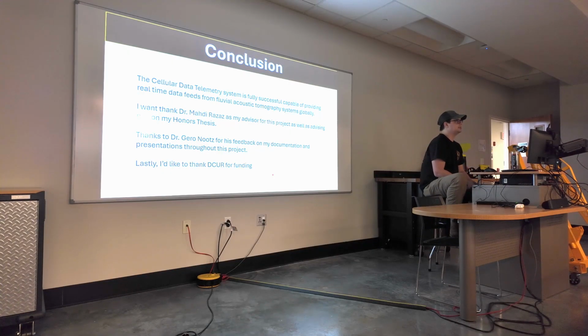But before I do that, I need to install a buck converter to power the system separately. It would use the same power that the logger is currently using, so it's the same battery, whole nine yards. But we wanted to boot up sooner than the Raspberry Pi that's there. So if it was just plugged into that Raspberry Pi, the Pi 2 would have to boot first, and then the Telepi would boot. We want this to boot before that, so I'm going to go direct to it, it's actually going to be on the toggle switch. Okay. That way, as soon as you turn the switch on, Telepi boots up, then it handles all the GPS aspect of the FAT system, and then the FAT's logger boots up, which would be a little more streamlined that way.